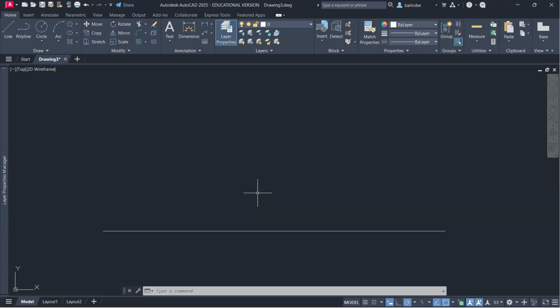If you are within a command, AutoCAD cannot execute another command. You need to exit that command by typing escape or the space bar or enter keys. Okay? So remember, if you're in a command, AutoCAD will be startled. It says, oh, you want me to zoom out, but I'm still making a line. Right? So if you understand that, it's easy for you to know what AutoCAD is doing. Just look at the prompt. See, AutoCAD was still asking you for the next line. It cannot execute a zoom.